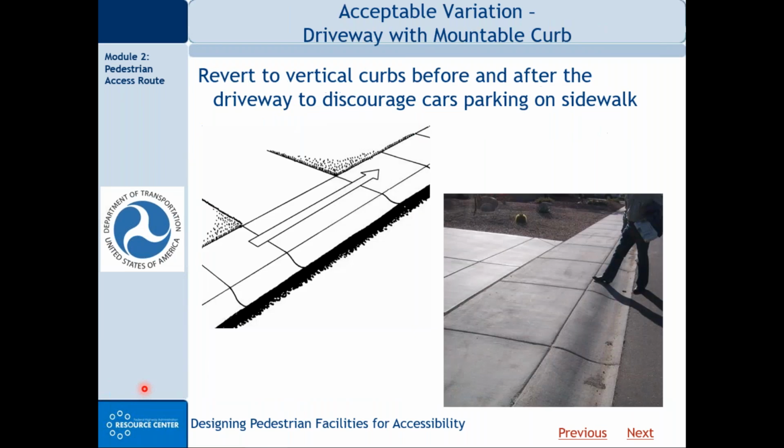Another approach, use a mountable curb. I mentioned yesterday, mountable curbs generally are frowned upon in ADA activities, but here's a case where I think this mountable curb probably works well for this driveway. And so, as I think I mentioned, I like to say never when it comes to ADA, because we again have to design for the specific context. And in some cases, this design that we would not normally recommend may be most appropriate for a specific location.